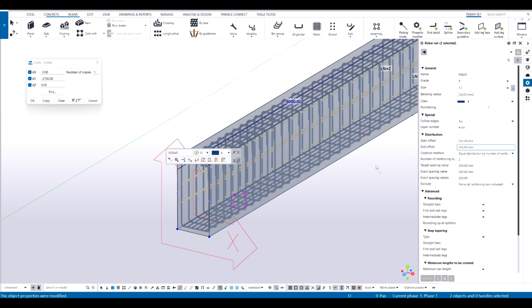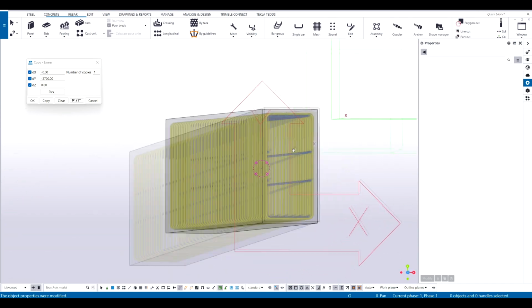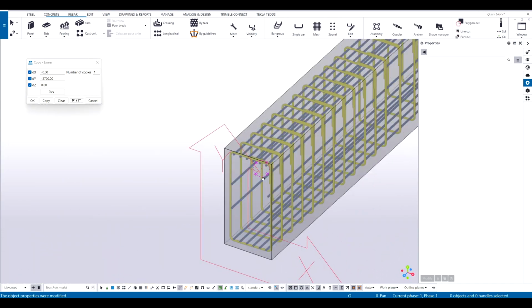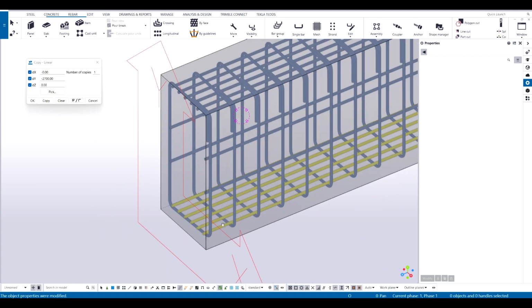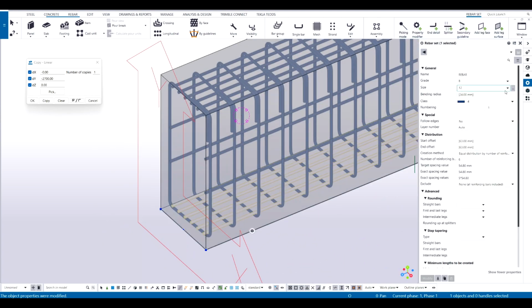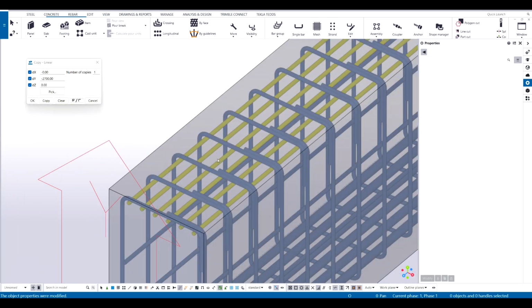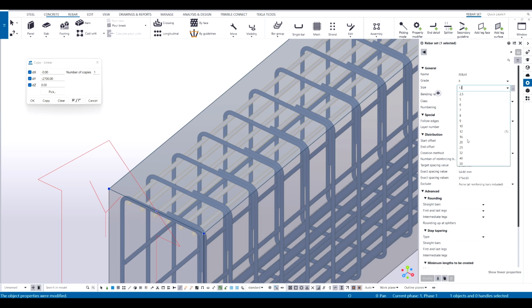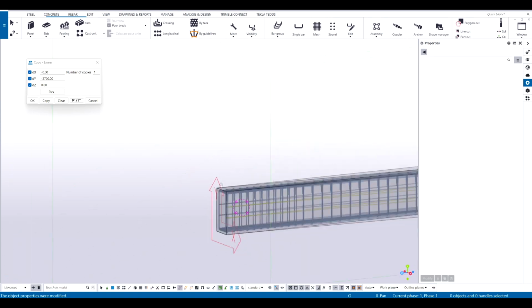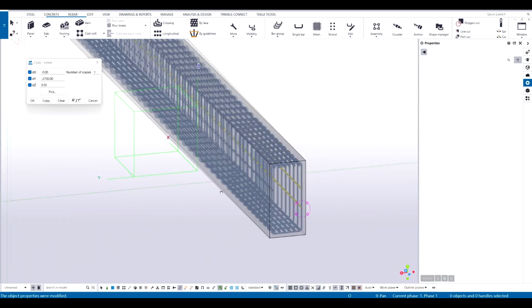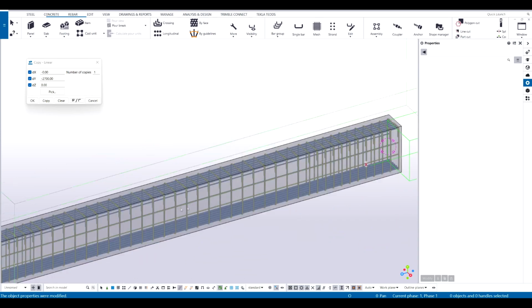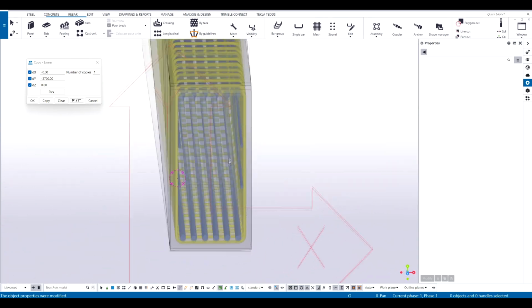Okay. So I got these bars in the middle. I'm going to have my other bars over here. Now the bottom, I won't be too happy with 12, so I'm going to make that 25s. Alright, it's heavy enough now. On the top, let's make these 16s. Let's go with 20s. Okay. So now my beam has quite a bit of reinforcement, chunky now.